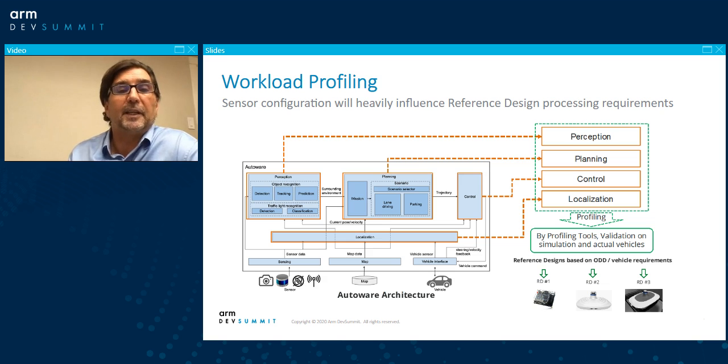You, of course, have the sensing that takes in all the information from the cameras, LiDARs, radars, inertial measurement units, and also GNSS. We have the mapping. In many of these applications, we use high definition maps to facilitate localization of the vehicle and understand where we are within the environment. And of course, you have the vehicle interface for control of the vehicle.